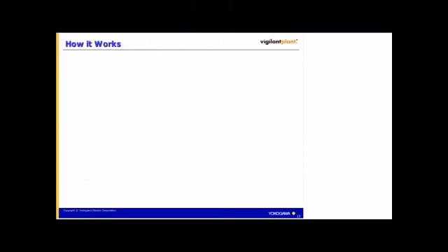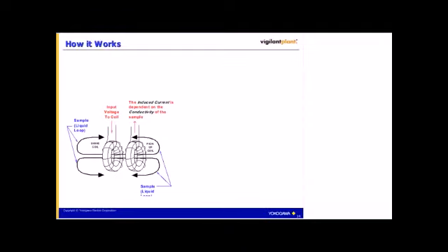Okay, how do they work? Well, their operation is similar to how a transformer works. When a voltage is applied to a coiled wire, a current flows through it and creates an electromagnetic field. This is what is done at the drive coil shown in the diagram. Conversely, an electromagnetic field will induce a voltage in a coil that is exposed to it. This is what happens at the pickup or receiver coil.